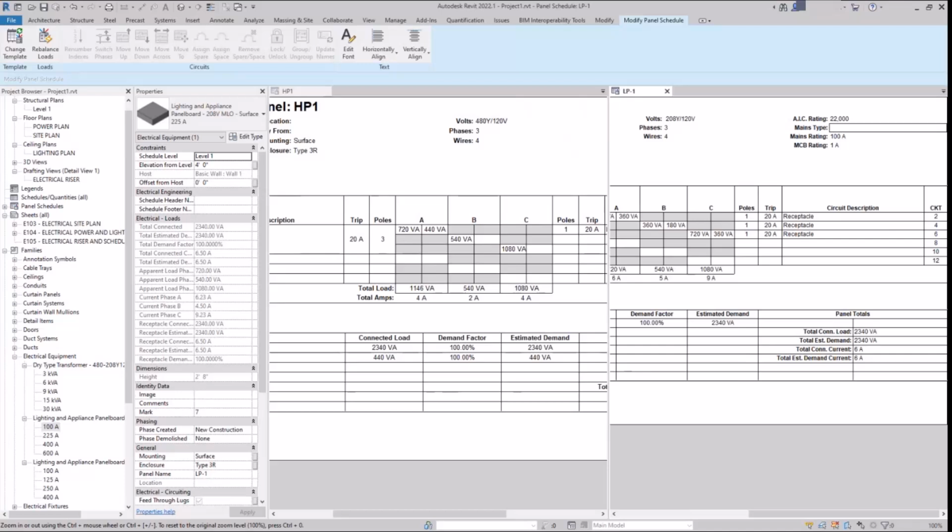There's no set of standard steps for each manufacturer. That's not how that works. So most of the time we'll say the minimum AIC rating. And that means this panel board can physically handle 22,000 amps opening. Like I can open 22,000 amps and stop this fault from occurring.